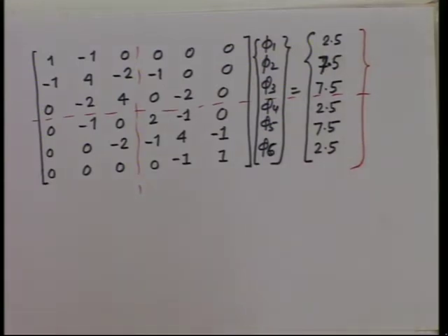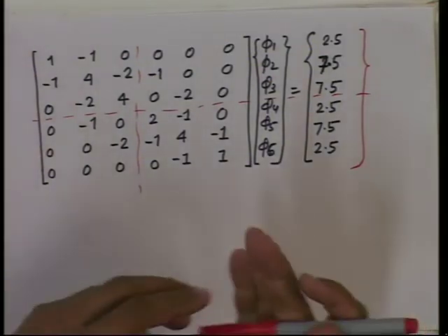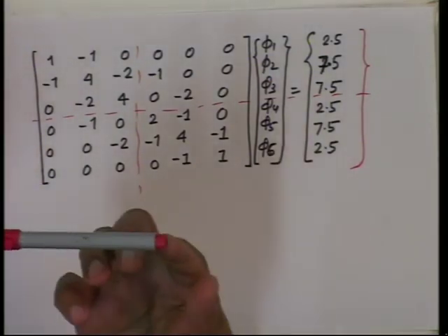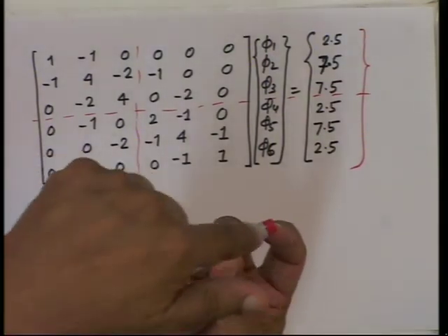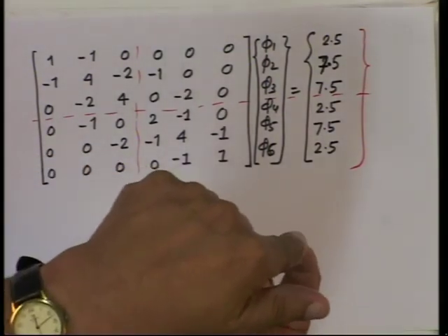it will not affect, because it is like support. Supposing you have a beam and displacement here is 0 and you also put a load. Will it deform the beam, that load? No, it is not, it is directly going to the support reaction, but reaction it will be reflected. Yes, in the reaction when you find out, then it should come. So, if the support is constrained, there is no displacement and the nodal force is there at the support, it is not contributing to the deformation. Okay. But then the reaction will come.